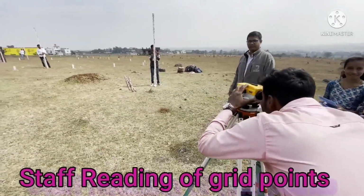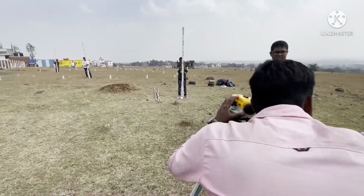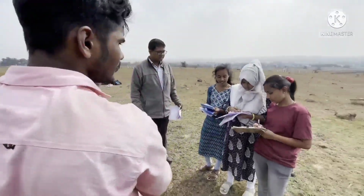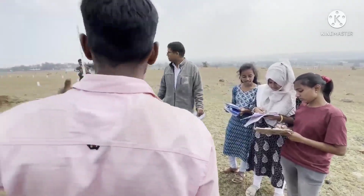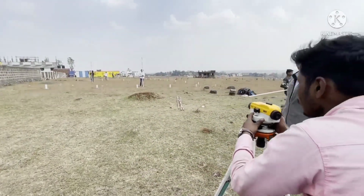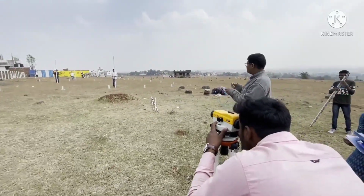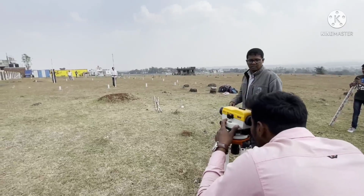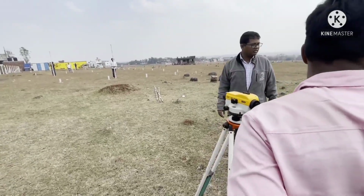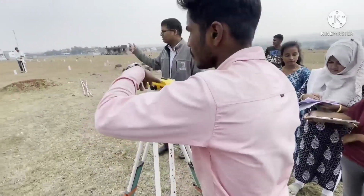So now we are going to start taking the staff readings of each and every grid point that we have placed on the ground, that is C0, L10, C0, L20, C0, L30, 40, 50. Correspondingly, the staff reading which I took during the fly leveling was of C0. Now further the staff reading will be taken of C0, L10, that will be written in the observation table.